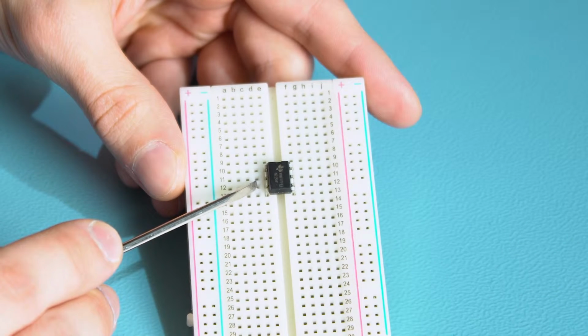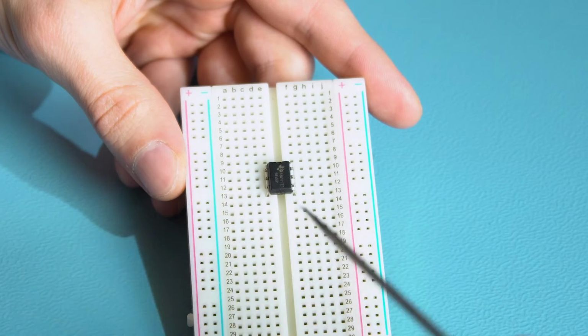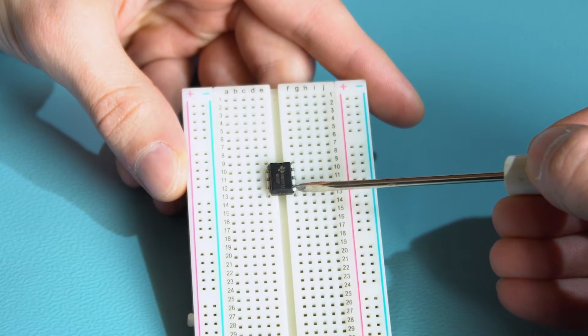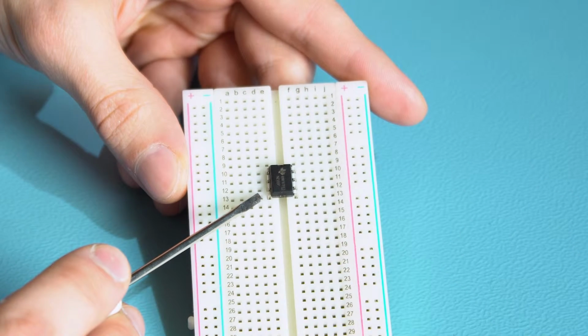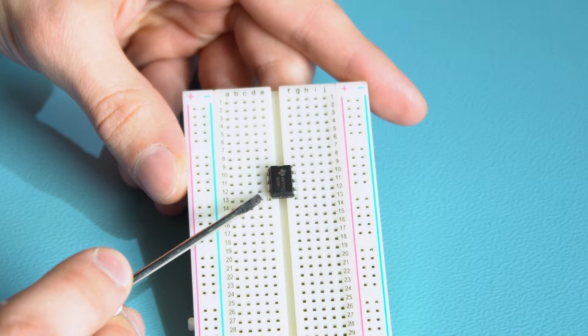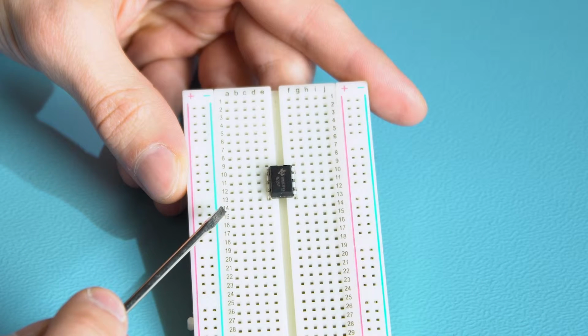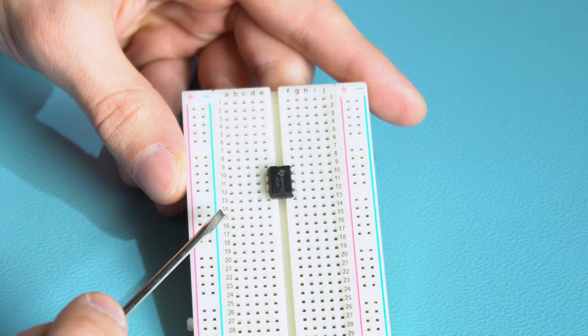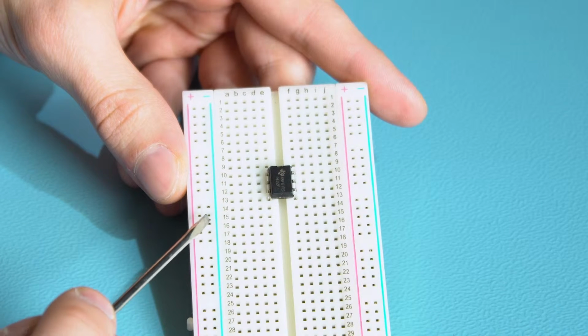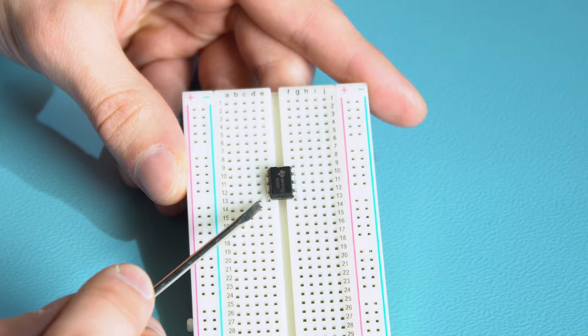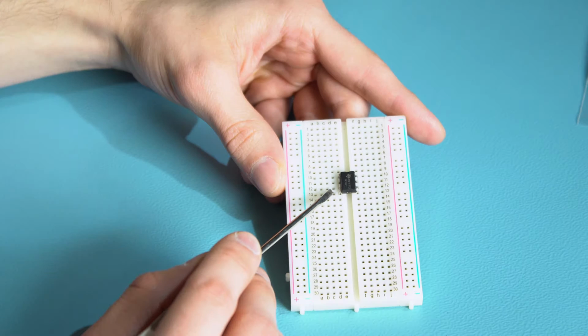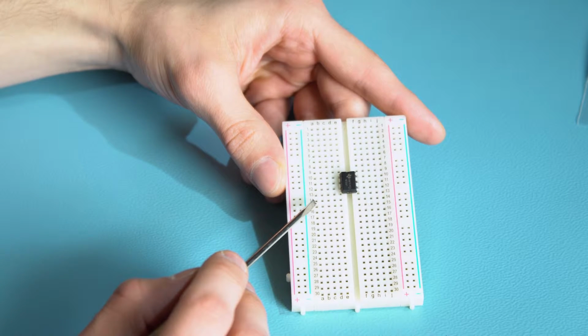If we exceed 2/3 of VCC on pin number 6, the comparator issues a high state for the reset input, causing a high state on this exit. The transistor turns on and the output will have a voltage close to 0. When we give the reset input a low state, the system will automatically turn on the transistor and display 0 on pin number 3. We will soon find out that NE555 can do a lot, and we will be happy to use it.